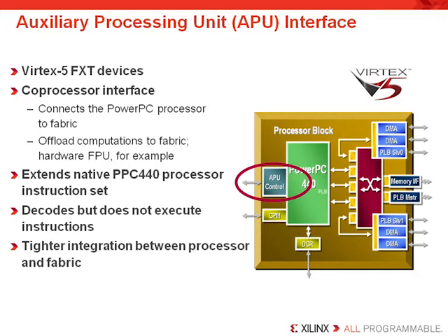In this case, what would happen is you would drive out of the processor's port, the APU port that is, you go to some dedicated hardware, do your arithmetic operation, and then feed that data back. And you can do that a lot faster rather than doing it in software, which might take lots and lots of clock cycles to actually complete the arithmetic. Now, integrating this with the DSP slice resources opens the co-processing space for embedded computing in a fraction of the normal hardware development time. And it's also built into the tools to be done relatively easily.